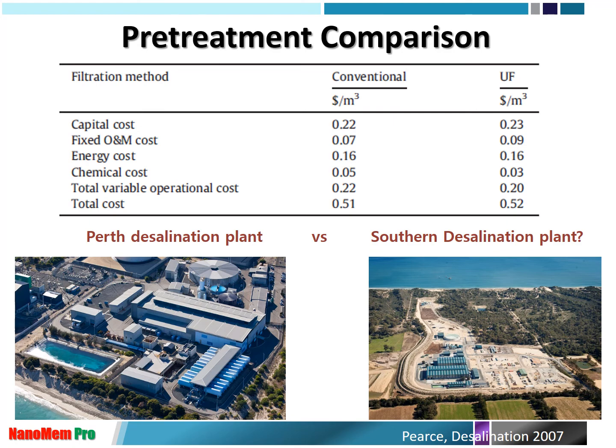That's the reason why they have a relatively very consistent RO operation when you utilize ultrafiltration pretreatment. On the other hand, at the Perth desalination plant, the sand filter has micrometer-size pores. So depending on your water quality, it will produce different quality of pretreatment permeate, which is the RO feed water. So it's not consistent, and therefore their RO performance fluctuates more compared to the Southern desalination plant. So that's their overall impression of ultrafiltration pretreatment and dual media filtration. Depending on your water quality, you can select your pretreatment process.